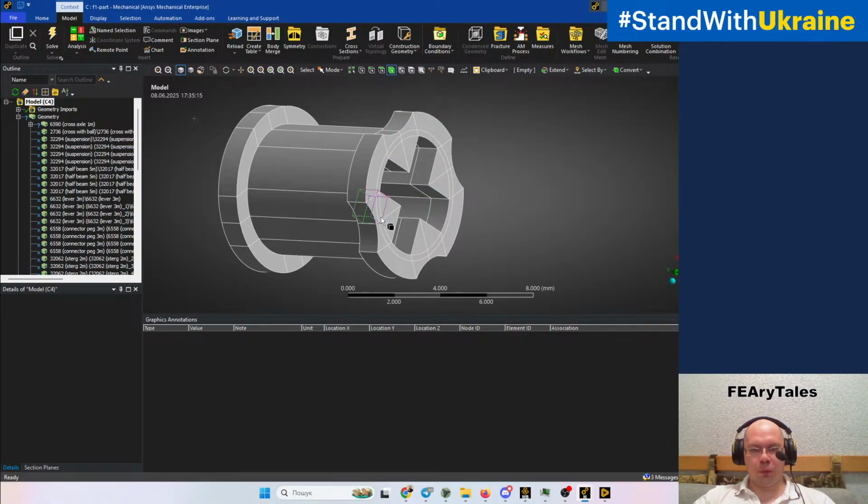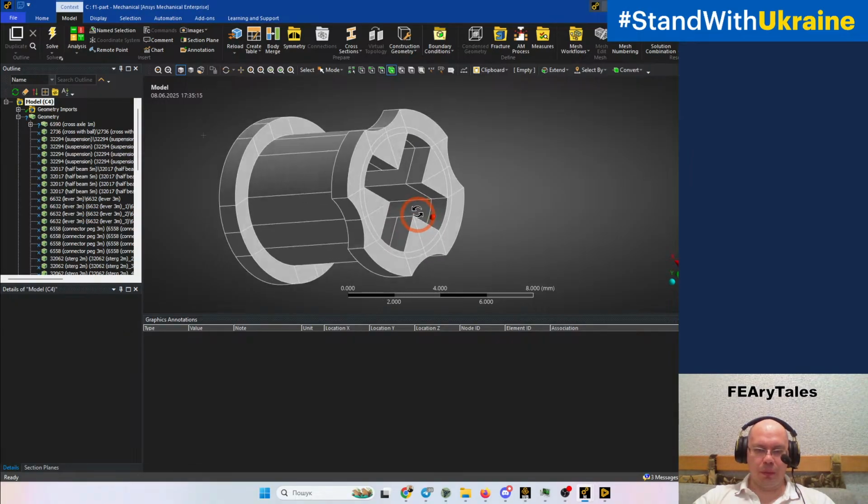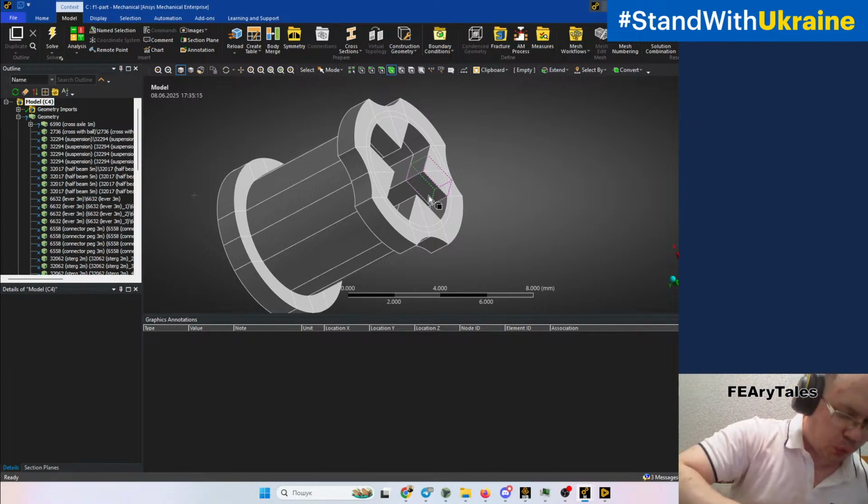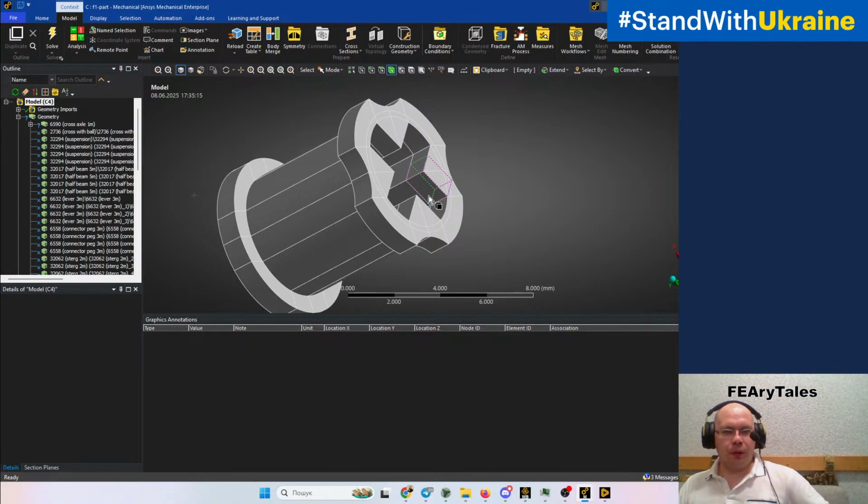But when we split some objects, we sometimes can obtain simpler geometry, and we can obtain more adequate mesh quality even with the same multi-zone method.